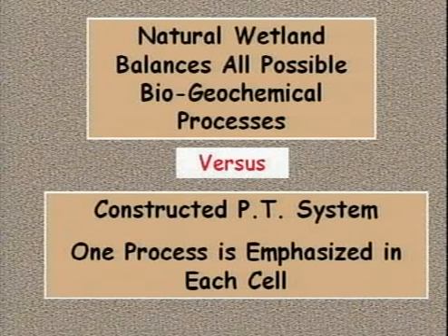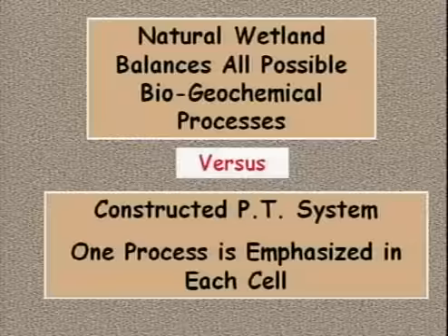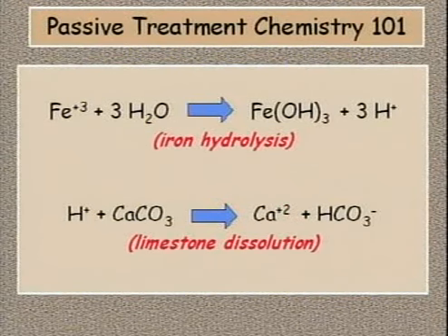This is the philosophy behind the sequential aspect of sequential ecological extraction we just discussed earlier. Despite the biological facets of passive treatment, standard geochemical reactions play a big role in how passive treatment systems work to remove metals.